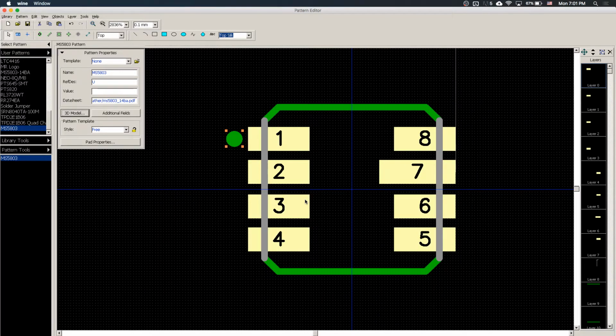So I think that is the last thing we want to do. We want to verify that all the dimensions are exactly the same as specified in the datasheet. So we use the measure tool. Usually you have a different tool for horizontal, vertical, free, and radius measurement. Horizontal and vertical are the ones we use most. Let's just measure the things.